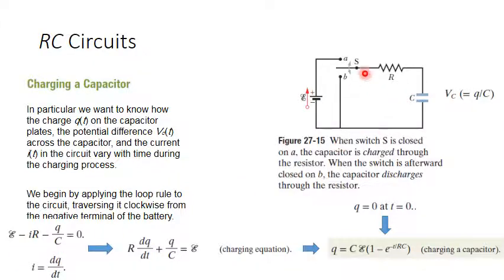If we have I, we can obtain the voltage or the potential difference at the resistance, I multiplied by R. If we have the potential at the source and the voltage drop at the resistance, we can obtain the voltage at the capacitor.